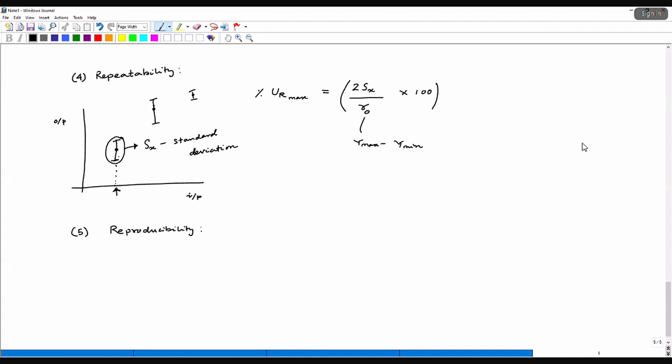Typically, in statistics, repeatability refers to the variation that you get in the data when the experiment is done by the same person using the same instrument under the same condition. It is basically some statistical measure because you repeat 100 times and you say that, okay, my repeatability is good or my repeatability is bad, because it is expressed in terms of percentage. If the standard deviation is very low, then my repeatability is very good. But reproducibility is a more qualitative term.